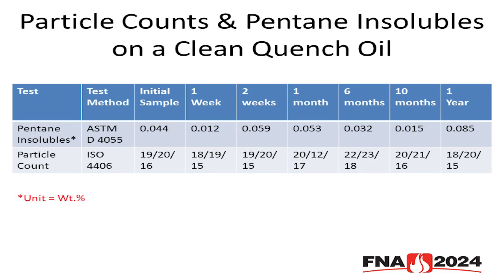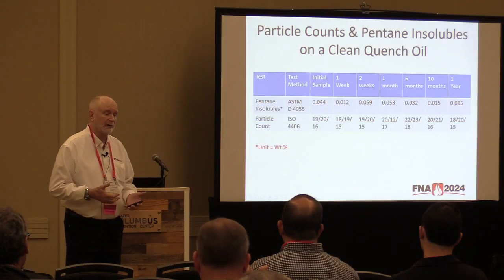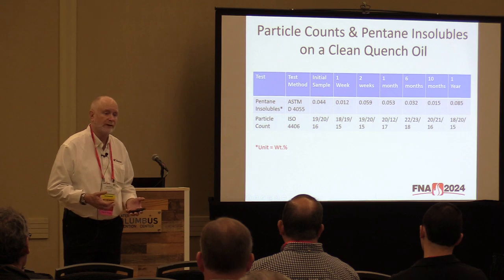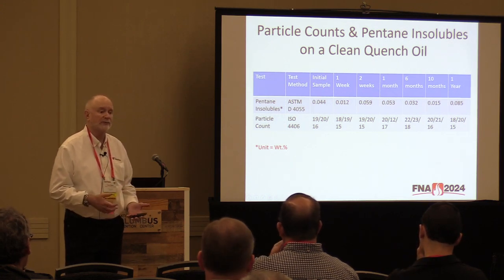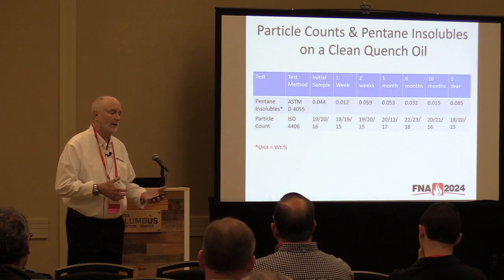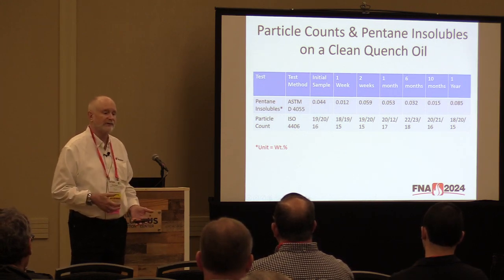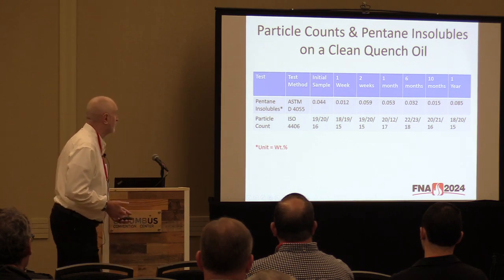We also worked with a customer on a 1-year study where they started off with a very clean furnace. It wasn't a new furnace. The furnace was 20 years old. But they cleaned it out as best they could. They opened up the heat exchanger, cleaned out the heat exchanger, and put fresh oil in it. This was a hot oil. We ran a study for a year to test the efficacy of their filter. And it was a 25 micron filter.